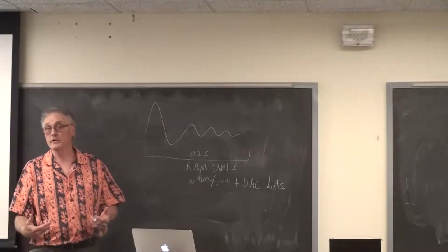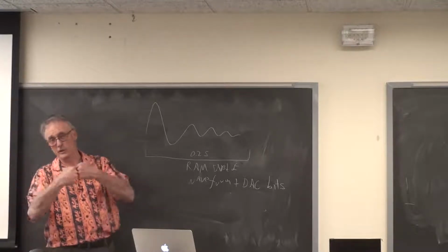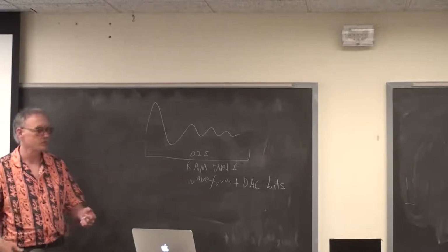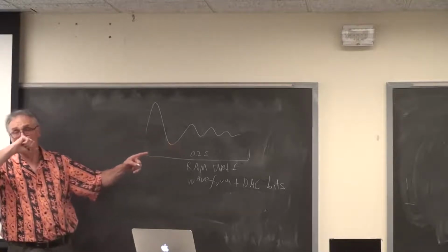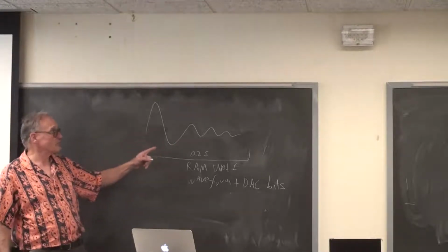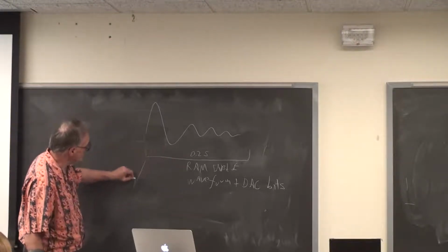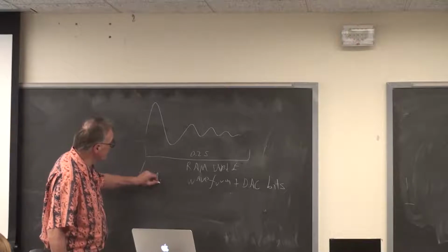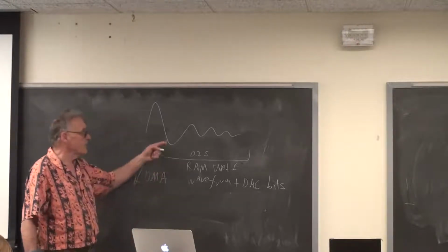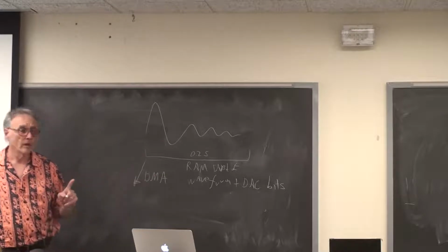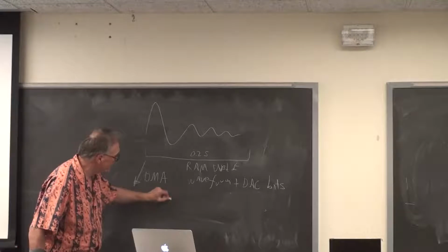Then what you're going to do when your code requires a sound effect, let's say when a ball collision occurs or the person loses or whatever the effect is, is you're going to turn on a DMA channel, which is going to copy this table into an SPI channel that's associated with the DAC.